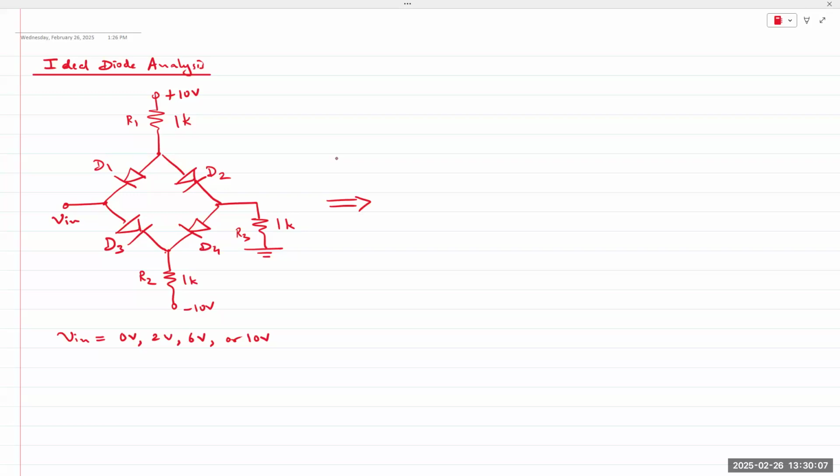Make sense? Minus 10 volts simply means that point is 10 volts below that same reference point. So if I draw out my reference point and show it as ground, when it shows ground in a circuit, it doesn't mean that it's physically connected to ground. That simply means it's a reference point in the circuit.